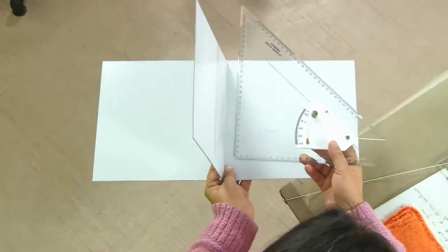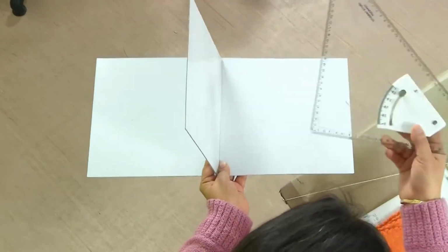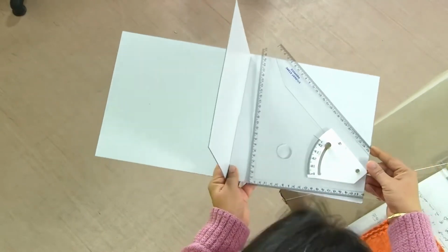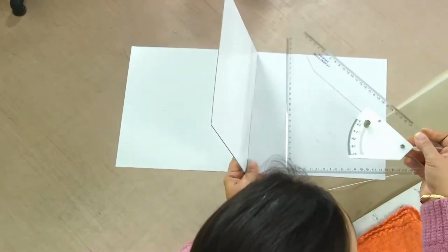Now if we kept it like this, it is perpendicular to VP and it is parallel to HP. It could be at any different height, it could be touching the VP, it could be in HP, whichever way, but it remains parallel to HP. So what do we see? We see the true shape of this plane in HP, which is the reference plane to which it is parallel. Now here we are assuming that this plane is perpendicular to VP and it is making an angle with HP. So this is something like this.